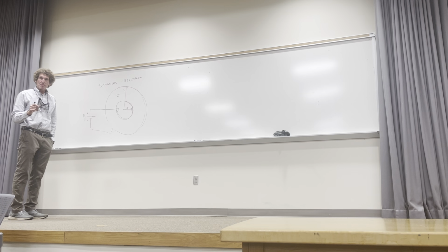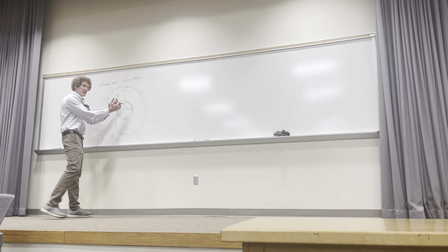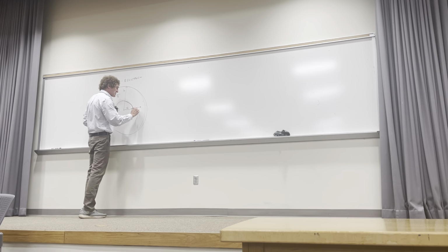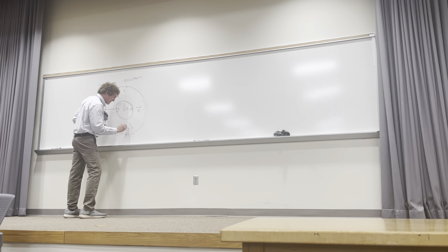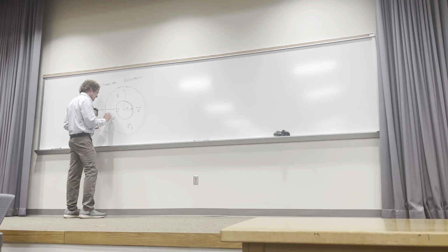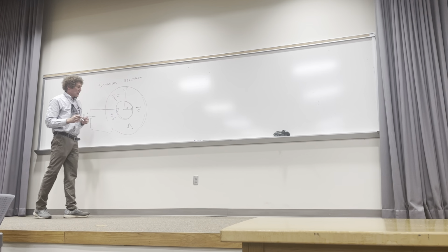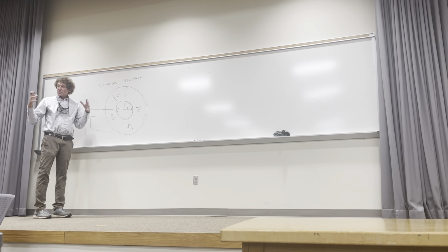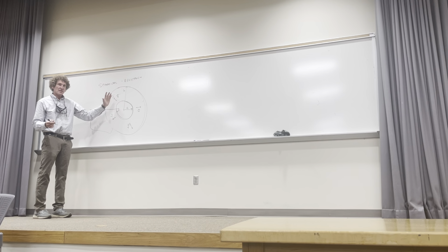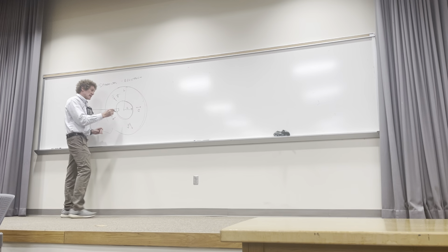Can you all imagine that? It's flowing from the inner conductor to the outer conductor. So J is going this way. I'm just trying to show you the direction it flows. Now here's the thing. The amount of current that's flowing from the inner to the outer conductor is not a function of radial distance, but the current density is. Let me get to that.